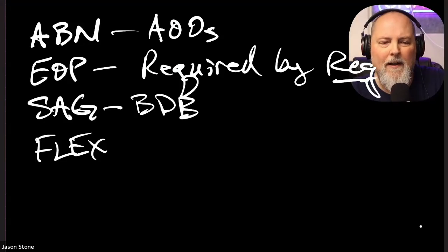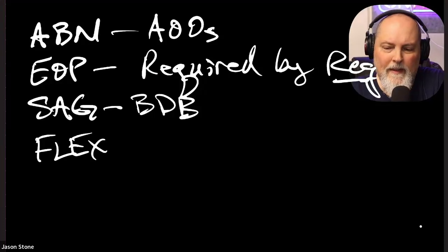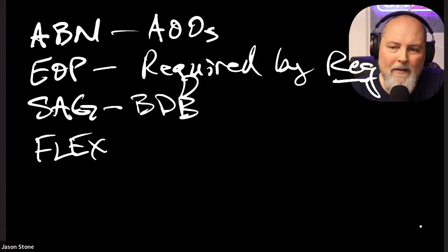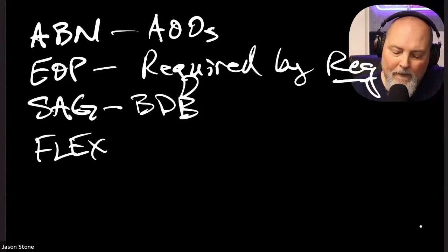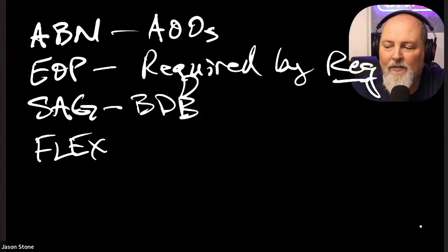And the keyword, tricky phrase, there's something on your quiz about this: when are they used? Well, they're used when core damage is happening, when fuel damage happens, or is imminent, or is about to happen. That's the key to getting into the SAGs. Once we start damaging the core, we're no longer in the EOPs. The EOPs assume core integrity, assume that we still have the fuel in place, safe, no fission product release, doing what it's supposed to be doing. So we have triggers that put us in the SAGs, the SAMGs, the Severe Accident Guidelines, initiated on specific degraded plant parameters.